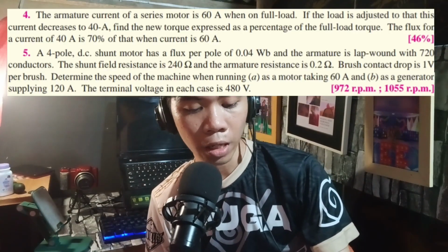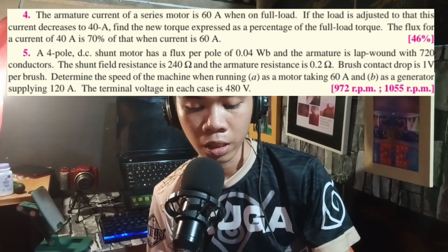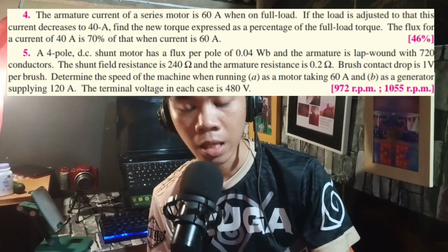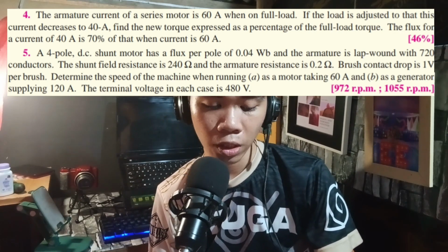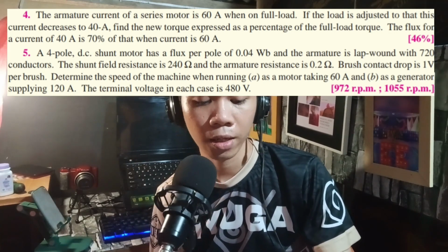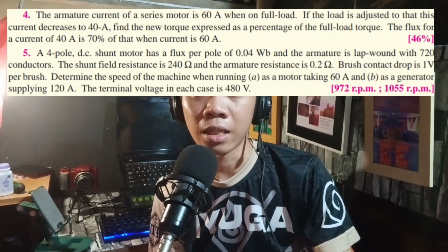Okay, babasahin na natin yung mga question na sasagutin natin para sa video. So ito yung unang tanong. The armature current of a series motor is 60 amperes when on full load. If the load is adjusted so that this current decreases to 40 amperes, find the new torque expressed as a percentage of the full load torque. The flux for a current of 40 amperes is 70% of that when the current is 60 amperes.